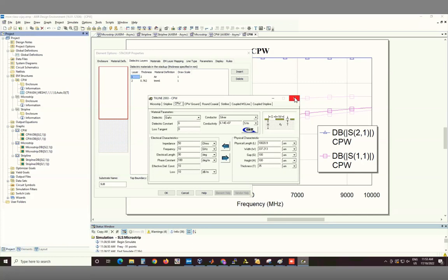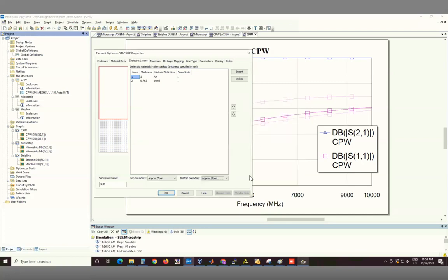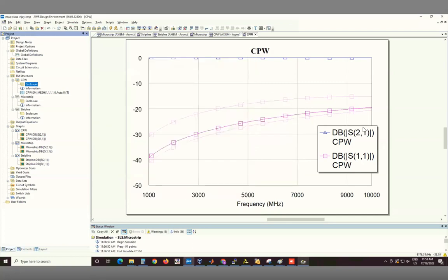So we can sort of verify that here, that the reflection has become worse when I did this. And that's consistent with the fact that I was initially having to increase the width of the central line to make the reflection better, which means I was making the impedance lower, but by removing the ground plane, the impedance has become higher, so it's slightly worse than the CPWG case.